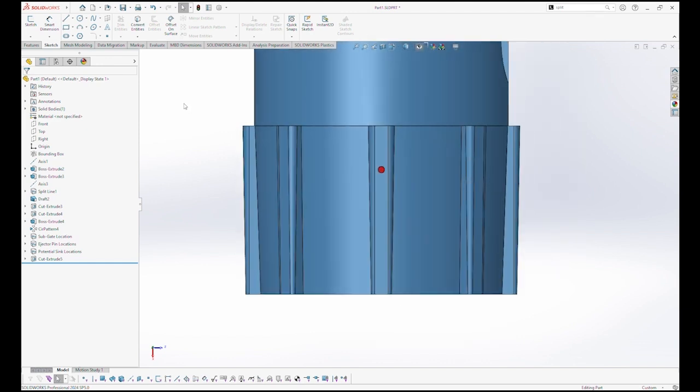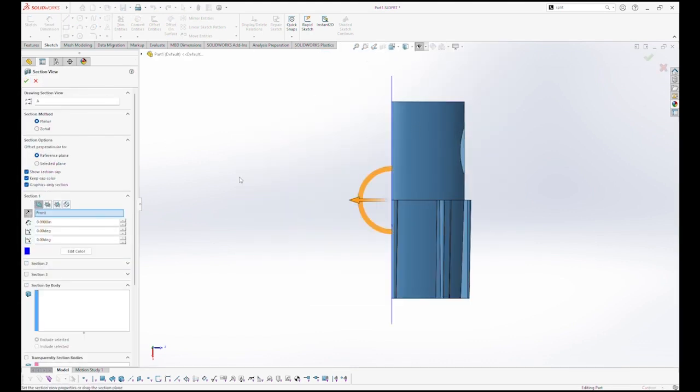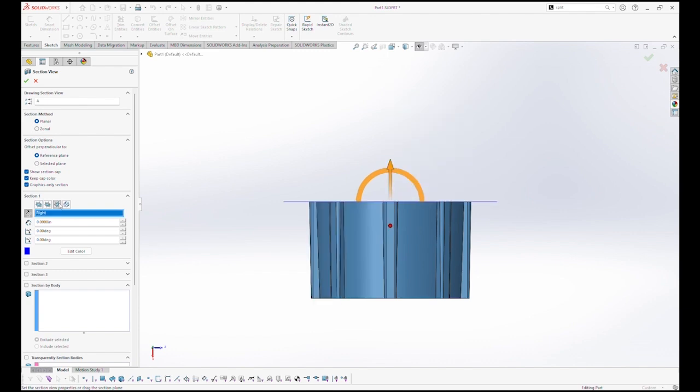And if draft is added, it makes it much easier to push the part out of the cavity. And so what I'm going to do is the same exact thing. I'm going to say that the right edge of that blue box that I'm drawing, and you can see in the part that it's drafted down, the minute those ejector pins push this just a little bit, it breaks that surface, and the part is much, much easier to get out, requiring much less force. And that reduction in force basically gives you a more repeatable and more desirable part. So now what I just showed you was the draft on the cavity. What I want to show you now,